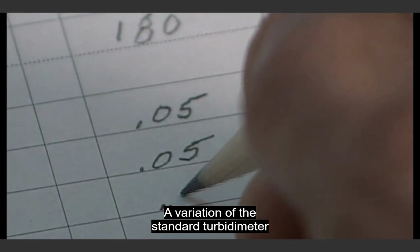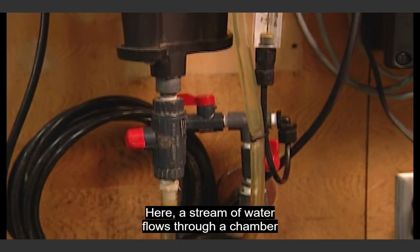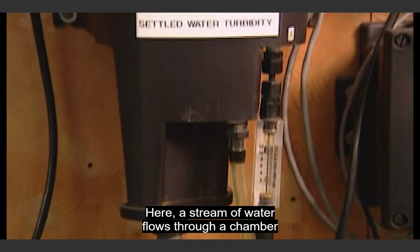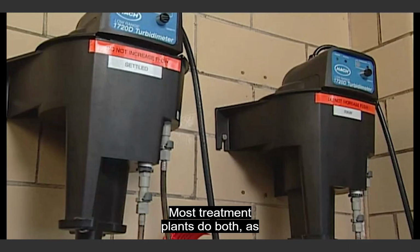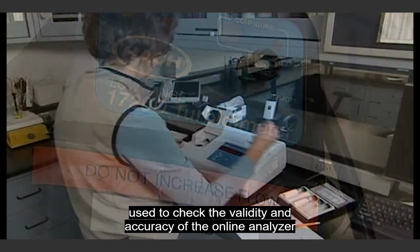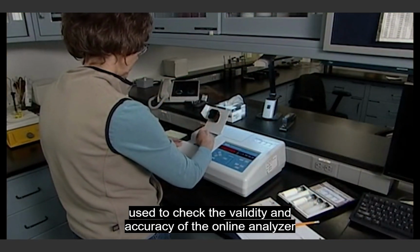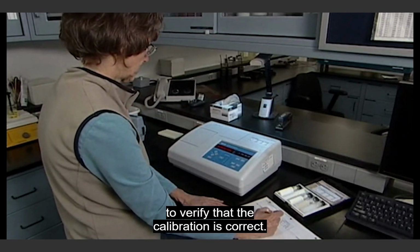Here, a light beam and detector measure turbidity. A variation of the standard turbidimeter is the online turbidimeter. Here, a stream of water flows through a chamber and turbidity is measured continuously. Most treatment plants do both, as the operator-obtained samples are used to check the validity and accuracy of the online analyzer to verify that the calibration is correct.